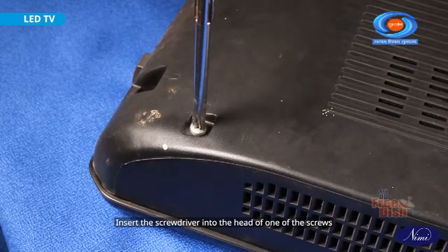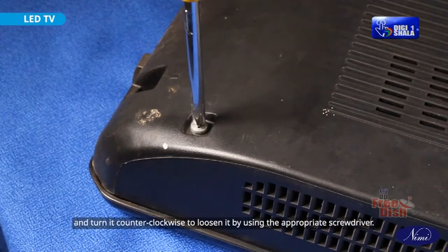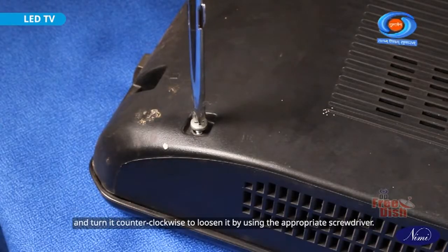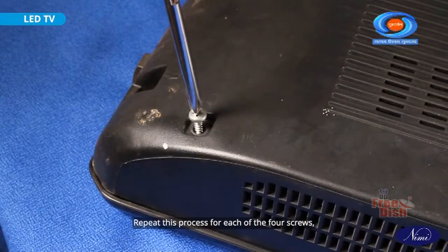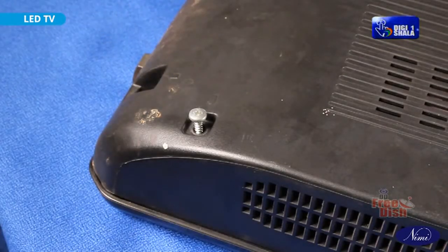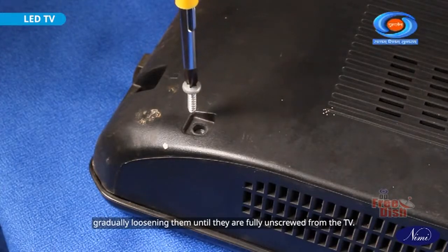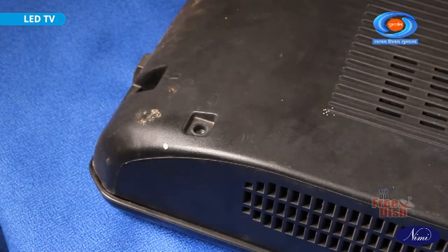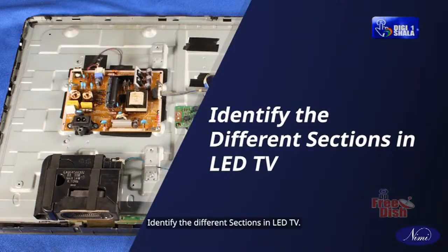Insert the screwdriver into the head of one of the screws and turn it counterclockwise to loosen it by using the appropriate screwdriver. Repeat this process for each of the 4 screws, gradually loosening them until they are fully unscrewed from the TV. Remove the outer cover to show the main body of the TV monitor. Identify the different sections in LED TV.